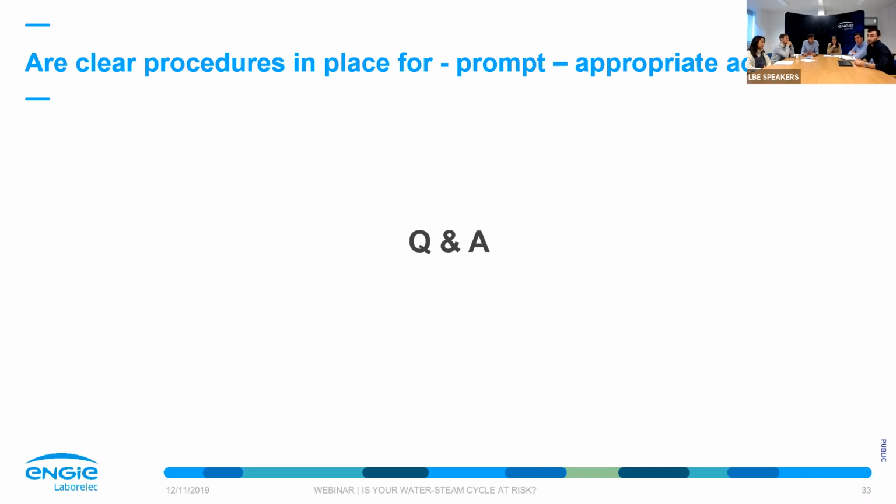Well, for automation, when you have a deviation, especially in boiler chemistry, I think it's maybe not the preferred way to automate everything, because you need to keep a human eye on the situation. If you have a deviation, this is not a normal situation. Something is going wrong with your chemistry and you need to troubleshoot the problem. Going the automated way, you can stabilize the chemistry with some automated blowdown, for example, but it will not address the source of the pollution, which is very important. You need to address the issue, not really the symptoms.